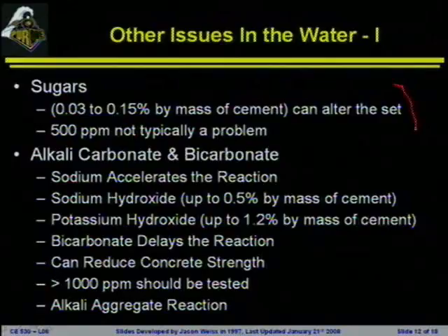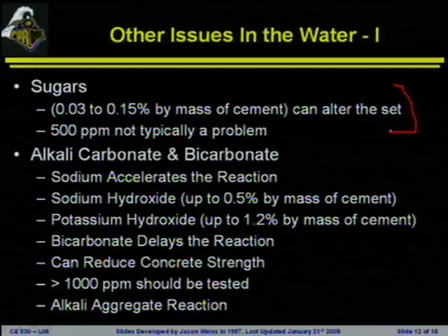Sugars will alter set. Sugars will reduce the set, if not completely kill the set. So if you take a 1 pound bag of sugar, throw it in the back of a ready-mix truck, you can pretty much make the concrete not set. And this is a big issue. If you see a ready-mix truck driver who's got a bag of sugar under the seat in the front, that's in case he gets stopped in traffic. He can basically take it up, throw it in the back of the truck, and you're not going to fill a drum full of hardened concrete. You would get concrete that would just never set or take an enormous amount of time to set.